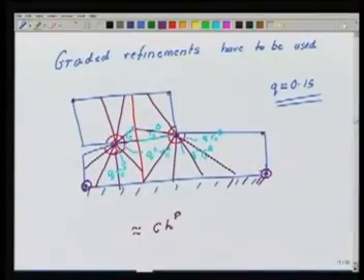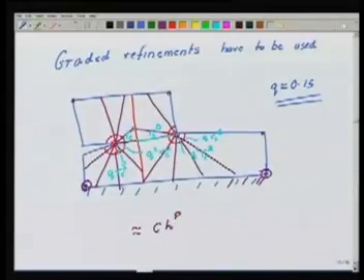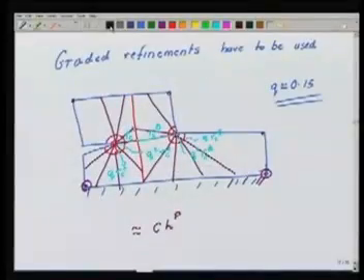So with this approach, with the graded refinements, we can capture the singular behavior of the solution. And just like I talked about earlier, in the vicinity of the crack tip, there are methods by which I can extract what is known as the stress intensity factor, the K, and we can extract that with much better accuracy if I use this kind of graded mesh. Okay, let's look at another issue which is of interest to us as engineers.